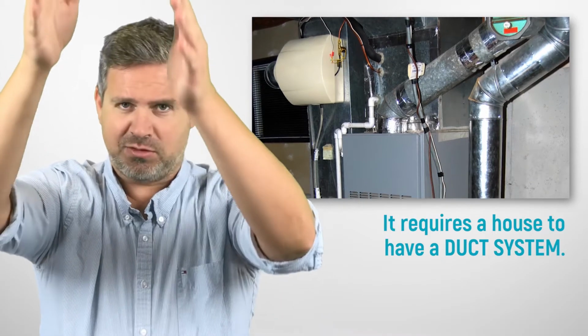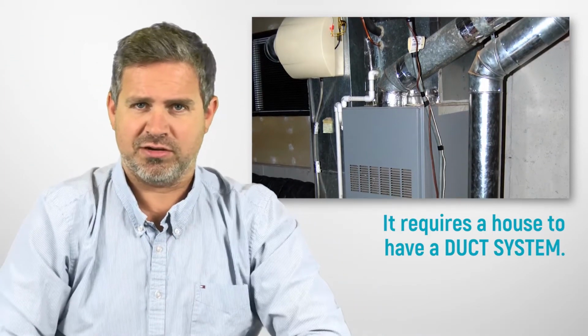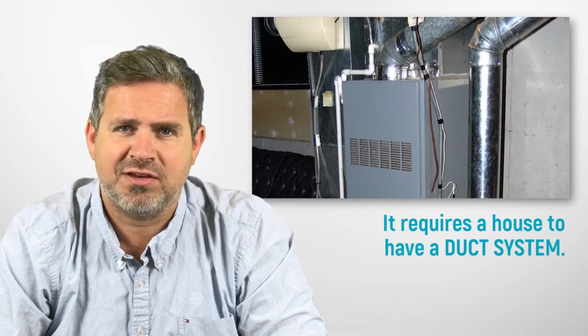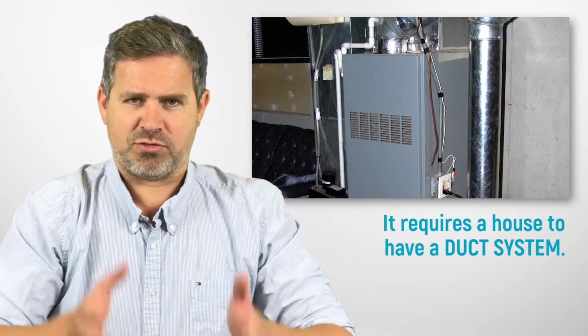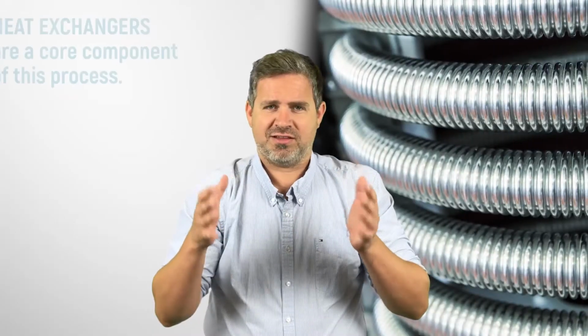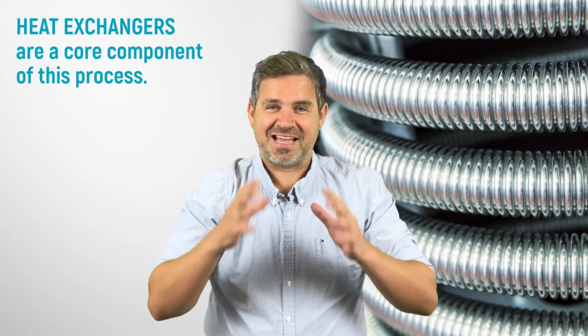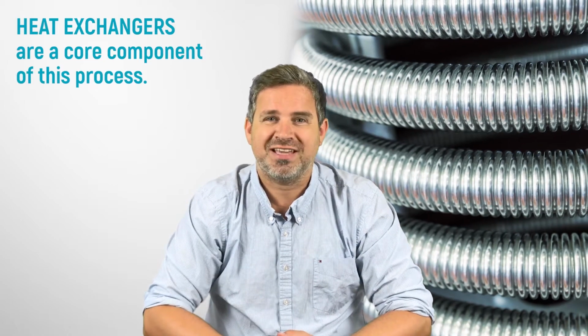It brings it down along the side of the furnace area. It sucks the cooler air into the furnace. Let's say it's coming back at the temperature of the house, maybe 70 degrees Fahrenheit. It puts it into the furnace and runs it through something called a heat exchanger. So that is the core element. That is the common connecting element between all sorts of forced air systems. There's something called a heat exchanger.